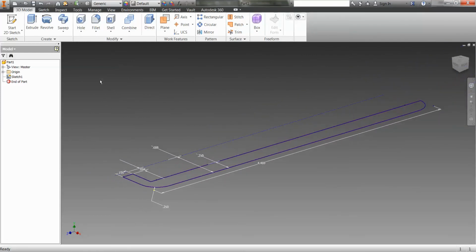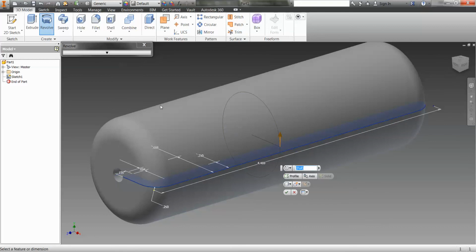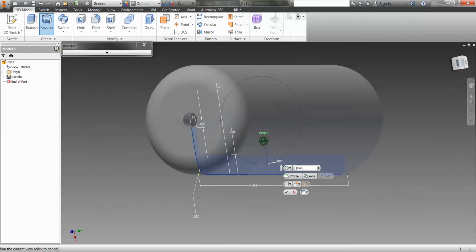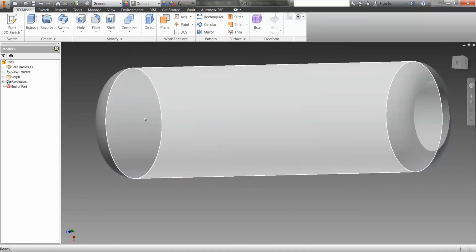And we're going to revolve this. So this is a new command, revolve. It selects a profile just like extrude, and then the missing bit is an axis. The axis is going to be that construction line that it revolves around. When we get that, it creates a shape all the way around and has the hole in the middle because of the way we set it up. So we've got that rubber handle. And we can go ahead and check that, and we're finished with that.